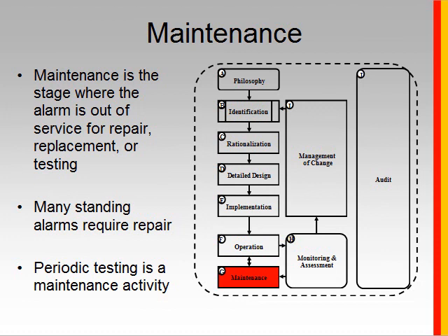In fact, one of the requirements of the standard is if the system provides this out-of-service capability, then the system needs to provide a listing of all the alarms that are out of service, which means you could look before you start up a piece of equipment like they did at Texas City and make sure that all the alarms that are critical to that piece of equipment are in fact ready to go, and you've got none of them on the out of service list.